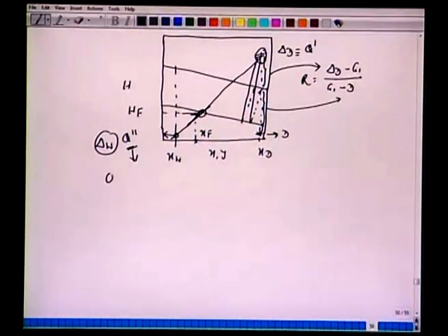Maybe from here we can calculate boiler load, or if we know the boiler load, we can mark this point, and we know the feed, we can draw like this, and wherever it intersects with the vertical line going through this xt, we can calculate Q dash. From this we can get condenser load.